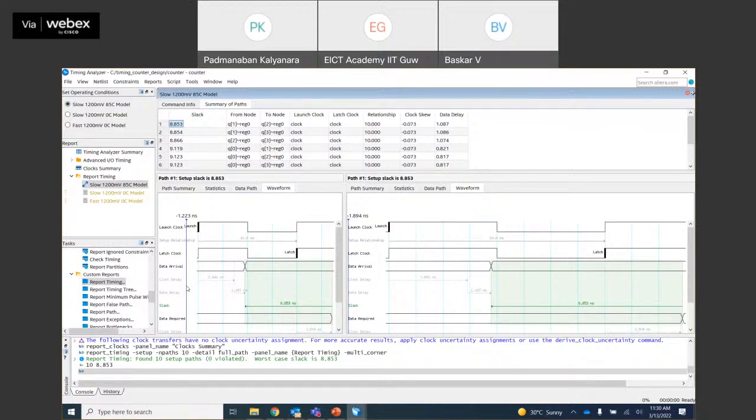Sometimes the tool will help you, but still we should be very, very careful and should not give any wrong information to the tool. Because if a constraint has a syntax error, the constraint will be ignored by the tool, and you may not have any impact of that command on the timing analysis. So it is always critical and important to try that in the GUI, apply that in the command prompt, get an idea, and then try to create your own set of constraints.